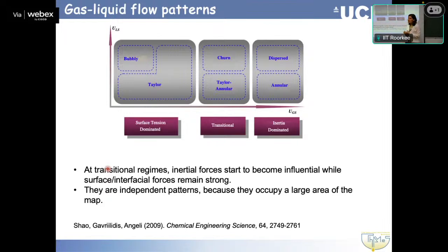Churn flow is like in between slug and annular flows, when the flow is quite mixed. You have to have quite high velocities and a lot of liquid to see that. It's more common in larger channels. So flow pattern is for both vertical and horizontal channel.